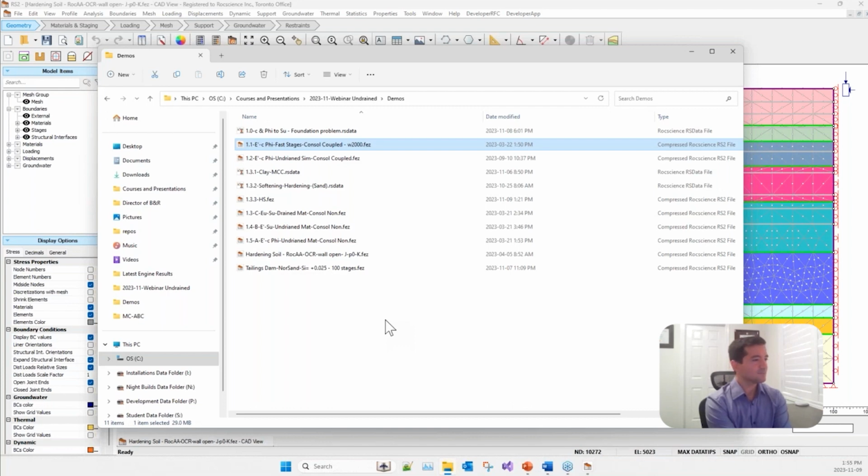Yes. Actually, this is one of the poll questions that we will have later on in terms of slope stability. Yes, you can have SSR analysis for drained and undrained cases. We don't have it for advanced material models, for example hardening soil; we don't have SSR for that. But for consolidation, drained, undrained, and all those scenarios that we have, if the material is one of those elasto-perfectly plastic ones, like Mohr-Coulomb, Drucker-Prager, or those kinds of materials, you have the SSR option.